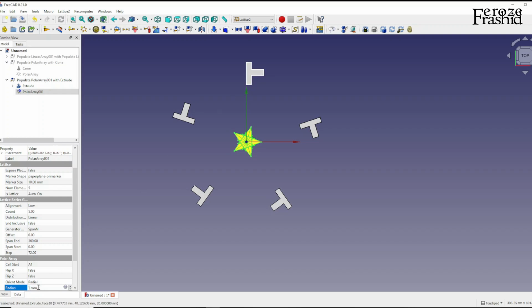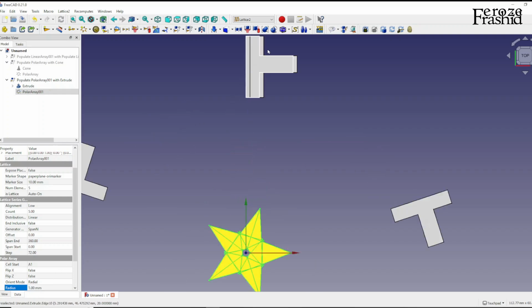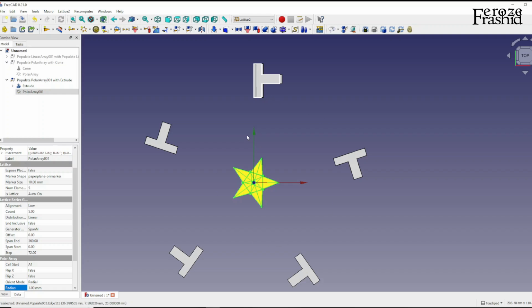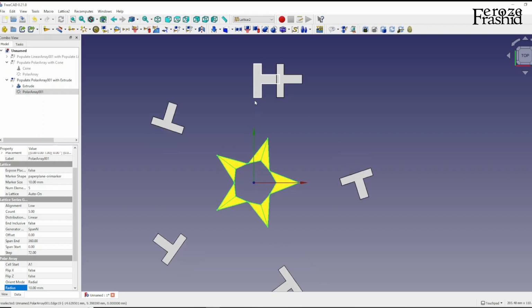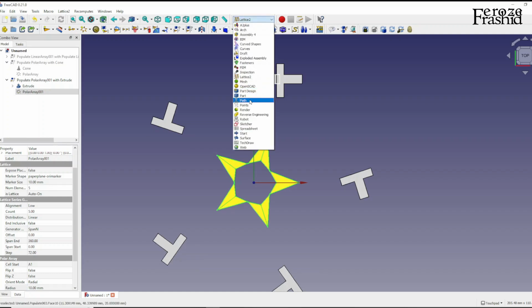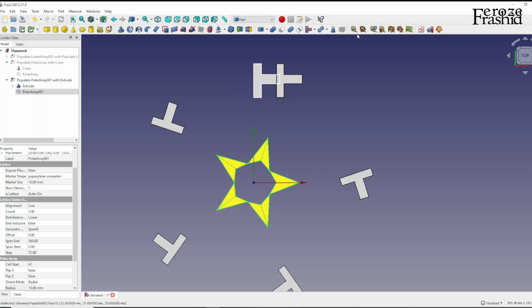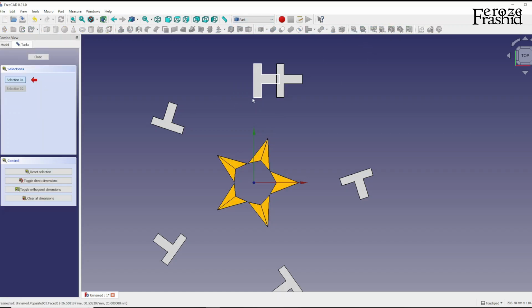If it is 1, the first object is moved 1 millimeter in linear fashion, and then the replication happens. So 10 means the distance between this point and this point is 10. Let's try that, see if that theory is working. So we take this point and this point. Yes, the distance between them is 10.